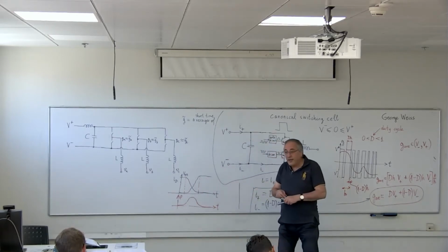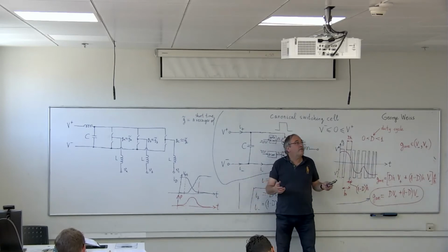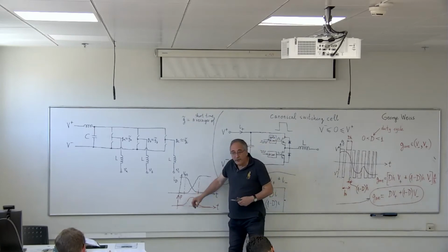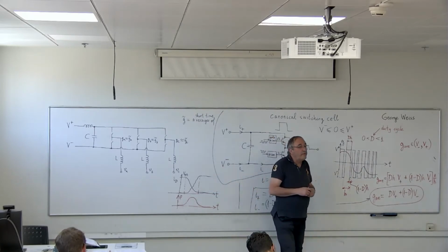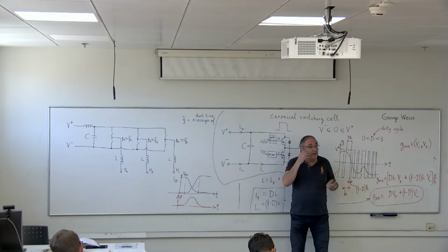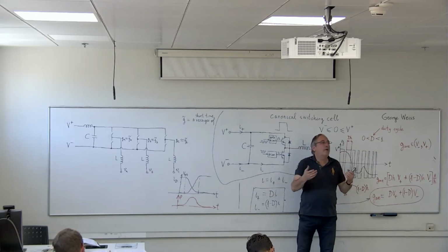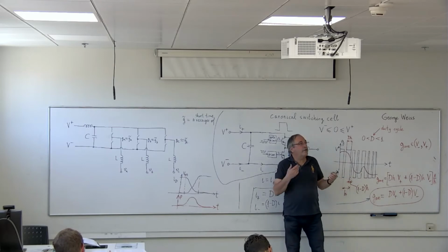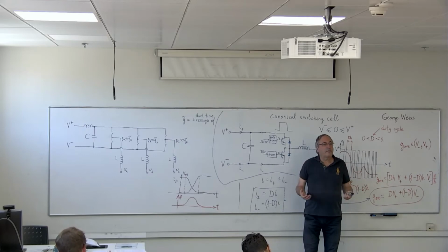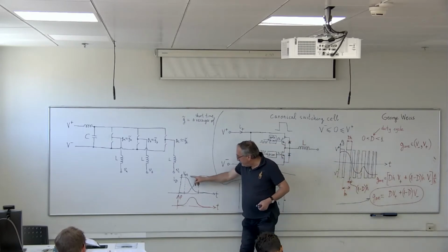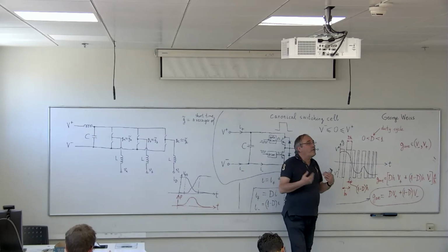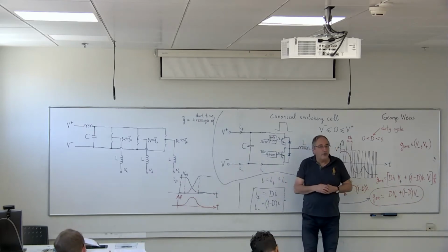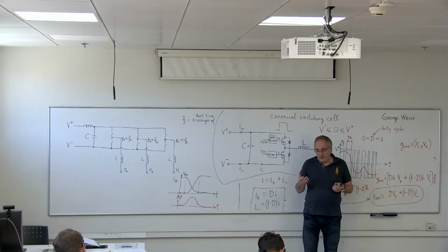The switching can take several tens of nanoseconds. So you want this switching to be short, and this is why even if you switch at, let's say, 10 kilohertz, which is not so high, you are usually searching for the fastest switch, which can operate at I don't know how many megahertz, because you want this switching to happen very fast, because then your losses will be small. The losses in practice mean that the MOSFET transistor becomes hot.